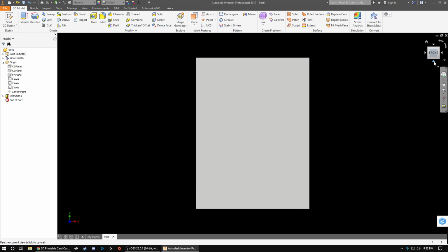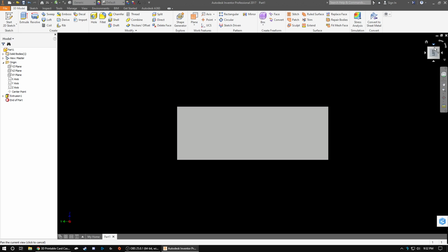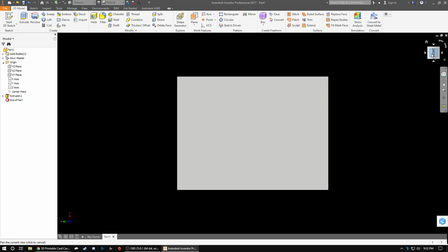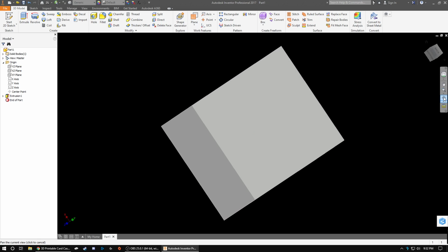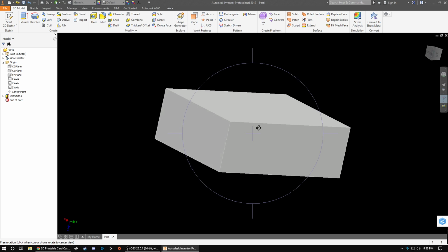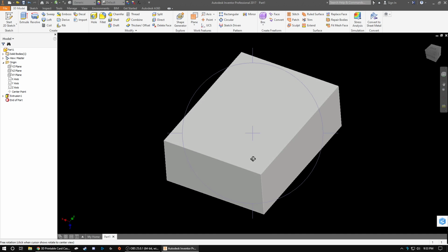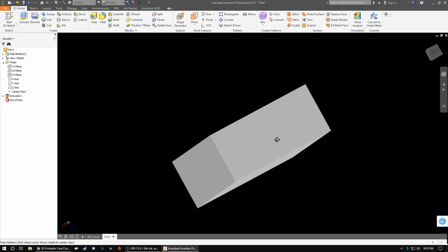So we can move things around by this box up at the top corner. We can click on edges here. We can click and drag it, and it'll rotate things here. Or we can use this little free orbit button over here to rotate things around. I personally like to use the F4 button because as you press it, it toggles it. You press and hold, so you can just toggle it and move things around. Double click, it centers things.